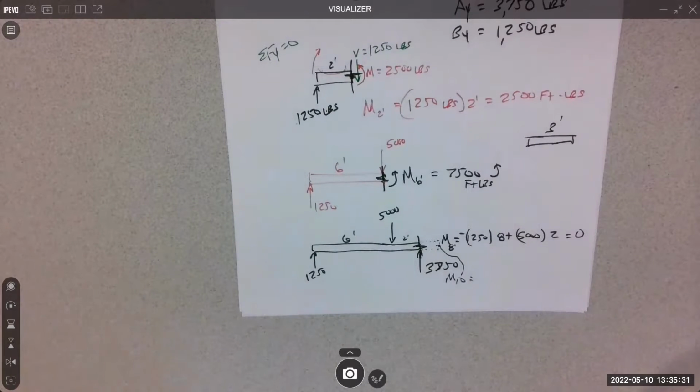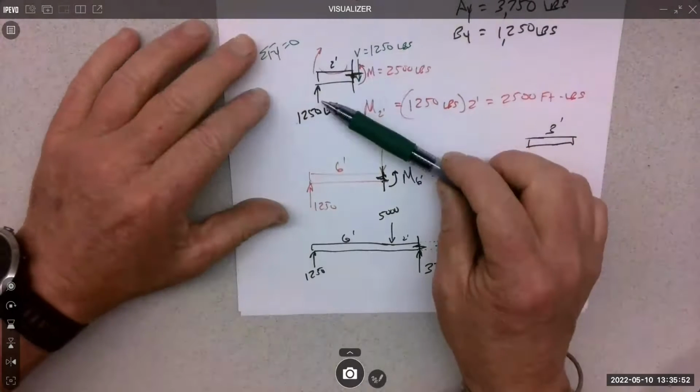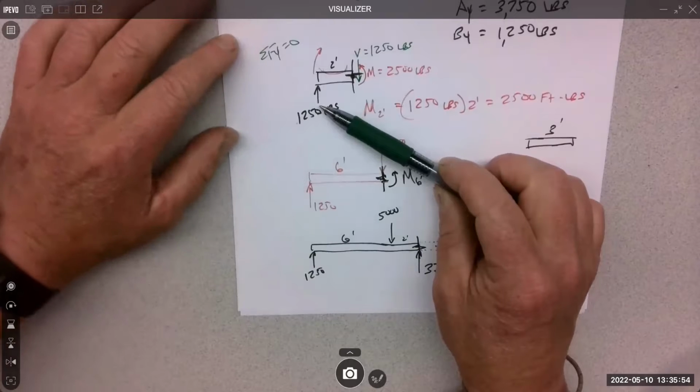So this is the force that's literally trying to shear off the beam. It's usually on a stress level, magnitudes lower than bending stress. So it's not typically a control, but we always check it. We always check this shear force and shear stress. It's just the force that balances whatever is going on to the left.